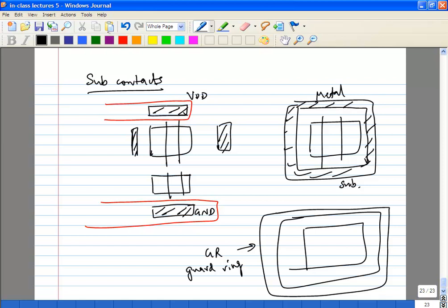So if you have a noisy thing, it will get pulled up through the metal and go straight to ground, which is through the low impedance path, okay. So typically a substrate ring will prevent your circuit from injecting noise into the substrate. A guard ring would protect your overall block from picking up things, okay.